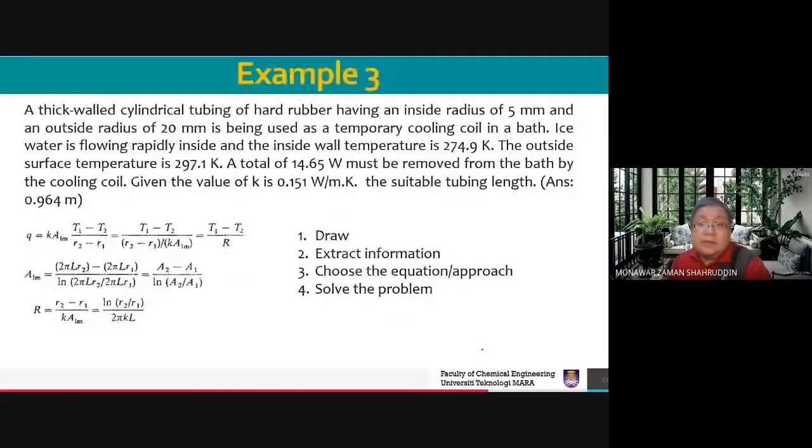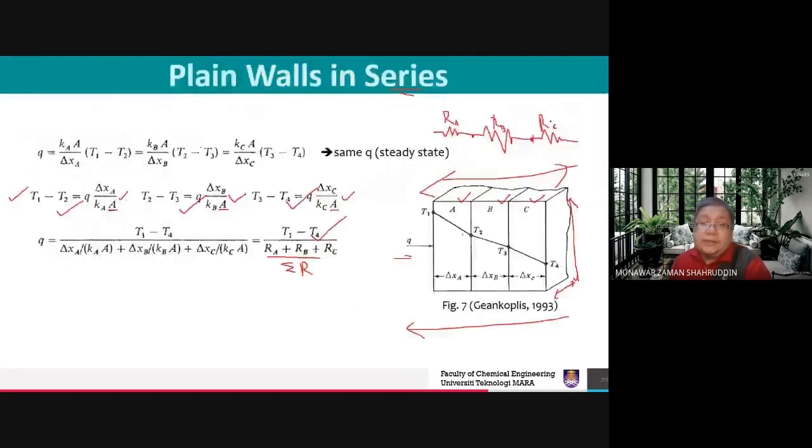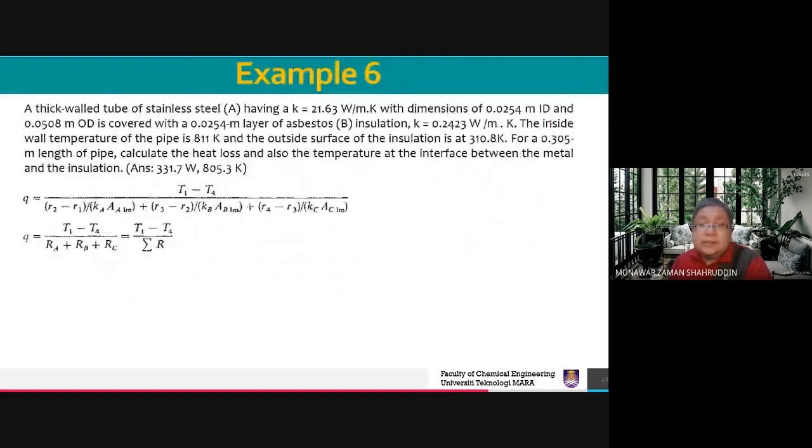But in this particular example, they will give you the internal diameter. So you have to do something with this value. You have to divide it by 2, unless you want to use pi L D as the area, and this might as well be the same.